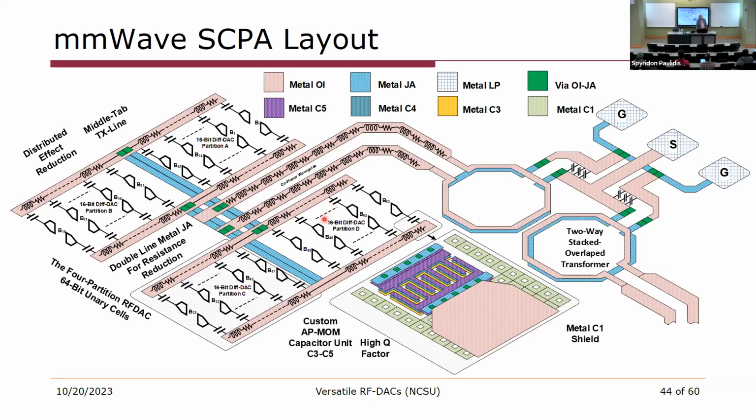So we decided to subdivide the array into 4 parallel arrays, and we kept the length of the transmission lines to be more or less lambda by 10 to minimize those transmission line effects. And then we have a common tap point where we sum all of the amplifiers into this tap, and then the transmission line effect doesn't matter as we propagate it to the output.